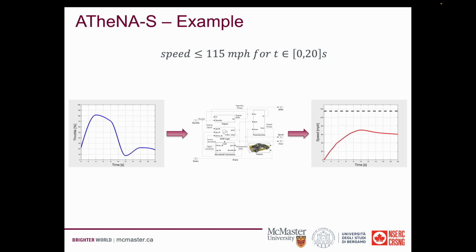These two fitness functions are complementary, as one targets the system input while the other targets the output. This way we can generate critical test cases faster than using either separately. We can see now that the iterative process is in action, with the system using test cases with an increasing throttle profile and an increasing maximum velocity, until the requirement is violated.